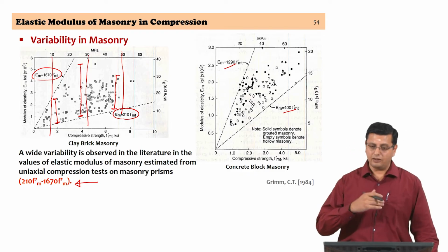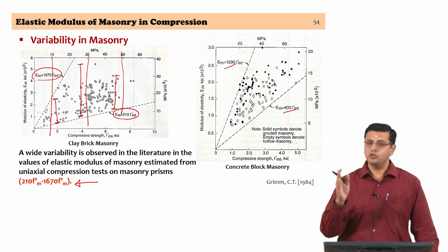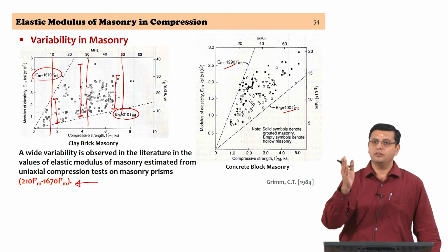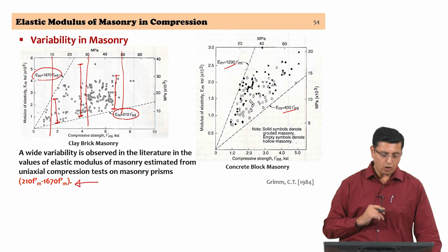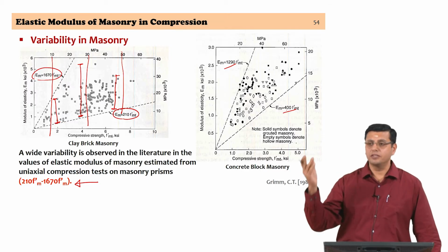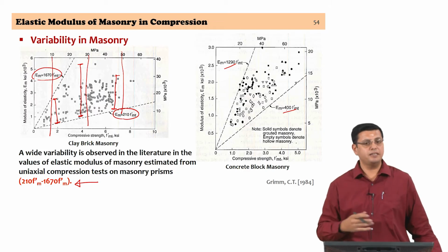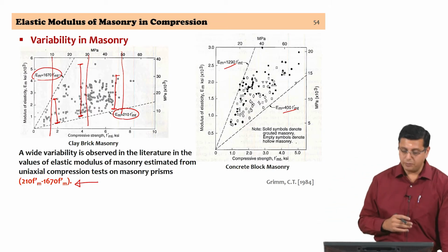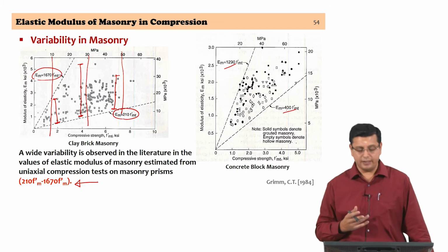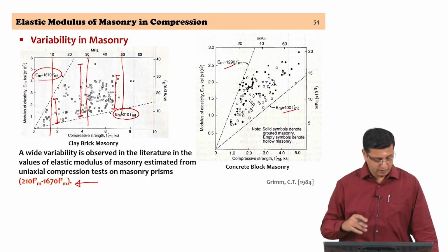That is a quantity that is going to be affected by your estimate of the modulus of elasticity from the stress strain curve. So, it depends a lot on the way the experiment is being carried out, and variability that can come in executing the experiment also.